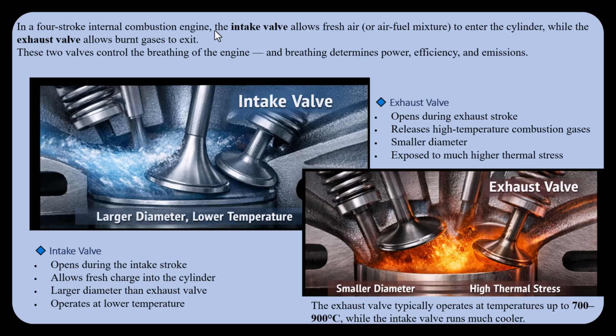The intake valve absolutely has a larger diameter than the exhaust valve and operates at lower temperature. And the exhaust valve opens during the exhaust stroke and releases high temperature combustion gases.